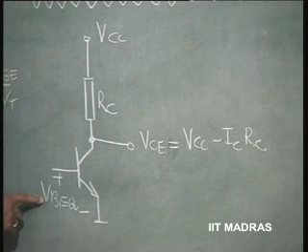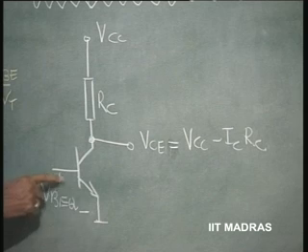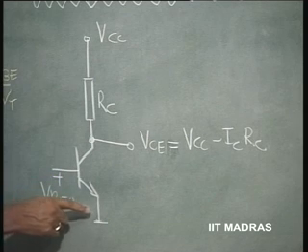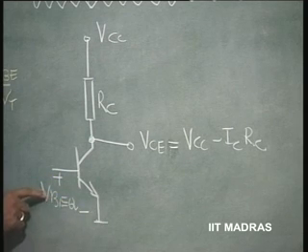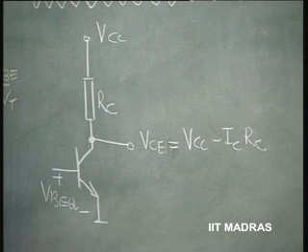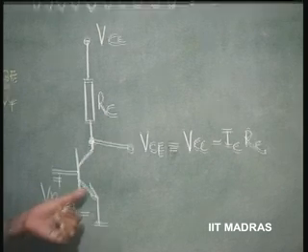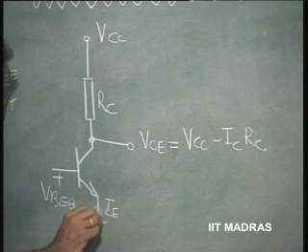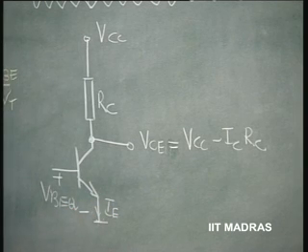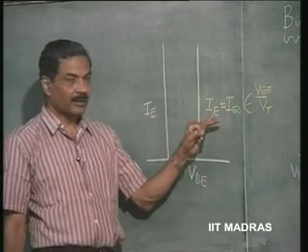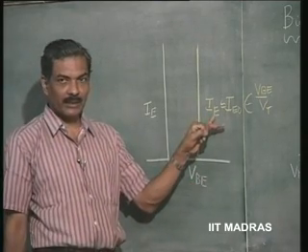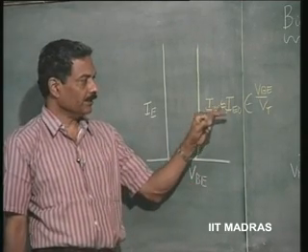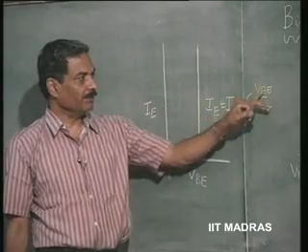And as far as forward bias is concerned, we have to forward bias this base with respect to emitter by an extent VBEQ, depending upon what current we want through the transistor. This is the emitter current. So, now emitter current and base to emitter voltage, they are related approximately by this relationship: IE is equal to IE naught exponent VBE by VT.